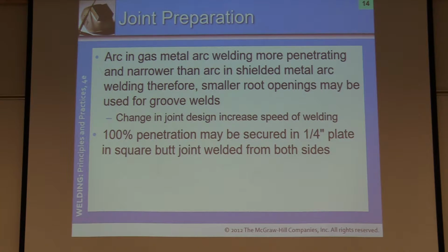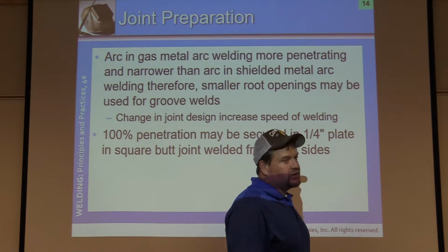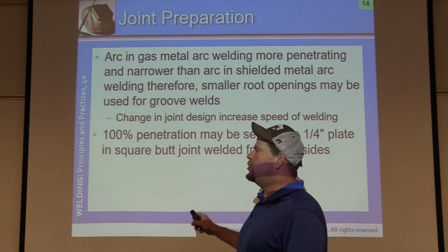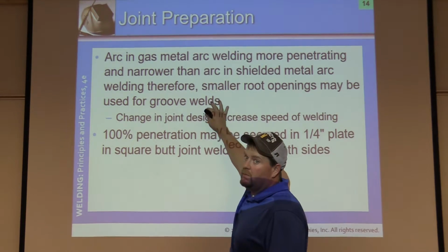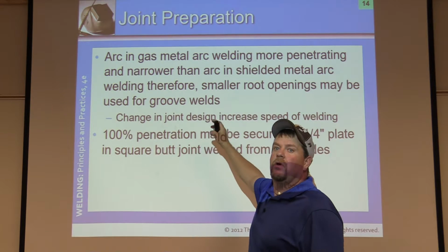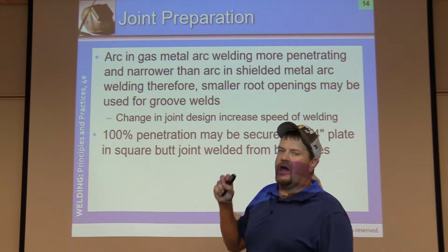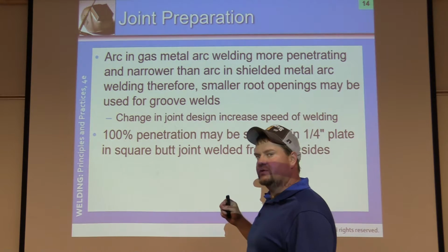The arc in gas metal arc welding is more penetrating and narrower than the arc in shielded metal arc welding. Therefore, smaller root openings may be used for groove welds. And you know, this can be a very big stipulation as well. By the time you get in here, make sure that you and I have had the talk in the shop about differences between root face or lands that we put on for different positions.